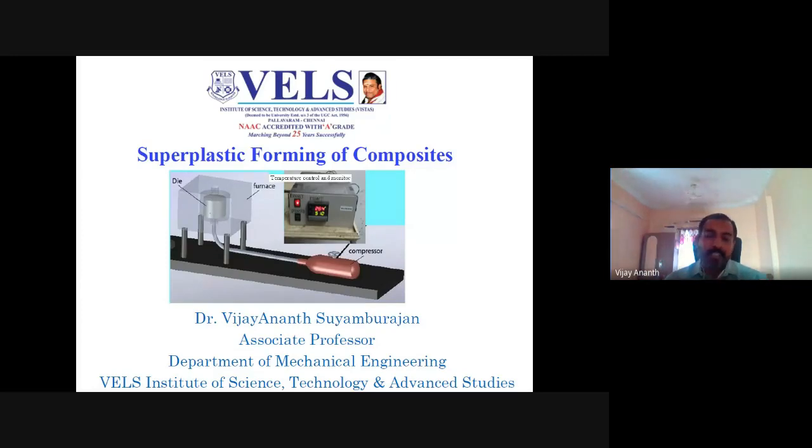Normally in the stress-strain diagram, up to the yield point we have the elastic region. After the yield point, up to the ultimate tensile strength, we have the formability range. Only in that range can metals be formed at room temperature, as in rolling or extrusion at room temperature, which is done above the yield point and below the ultimate tensile strength.